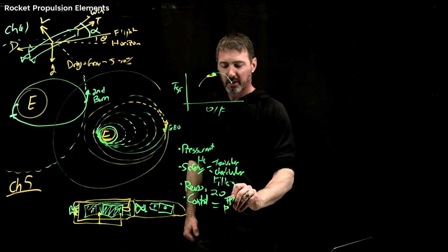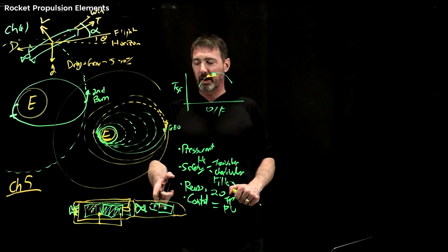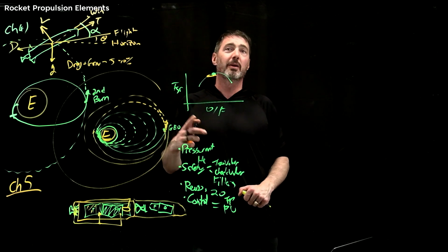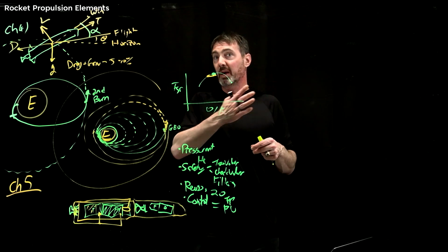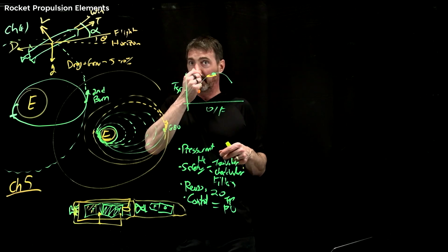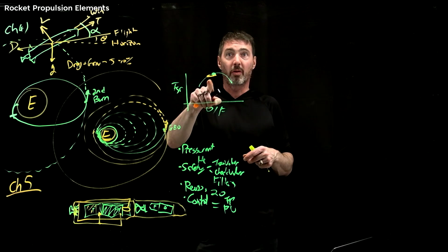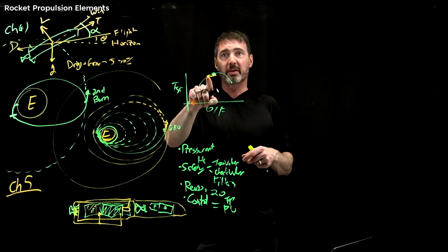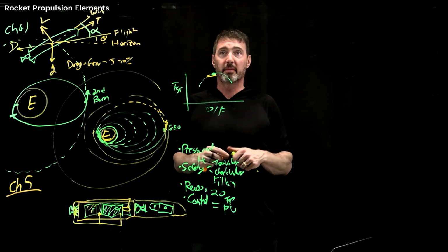But there's also a thing called propellant utilization. You want to make sure you use all of your propellant. So you're going to have some sort of liquid line measurement, which can be hard because they can be massive. And so you want to make sure you're draining all of your propellant. And again, back to maybe this curve, on some logic, it might be better to go over here to drain it, for some reason, if you're draining slowly or you had a misload.